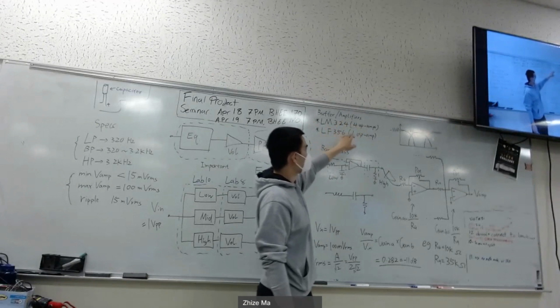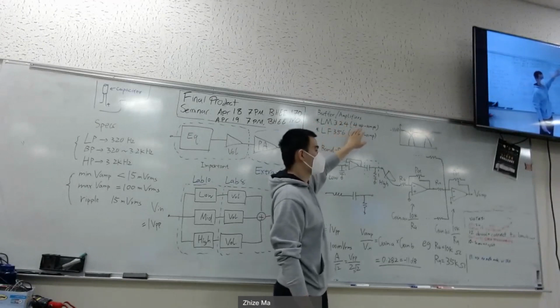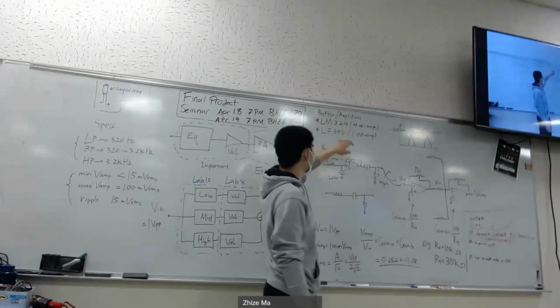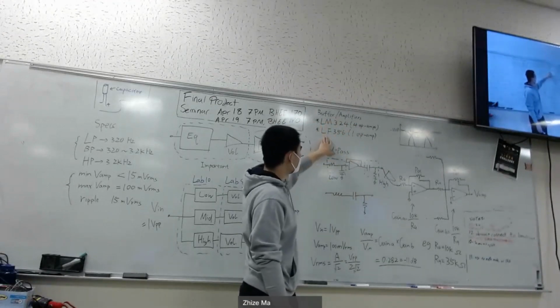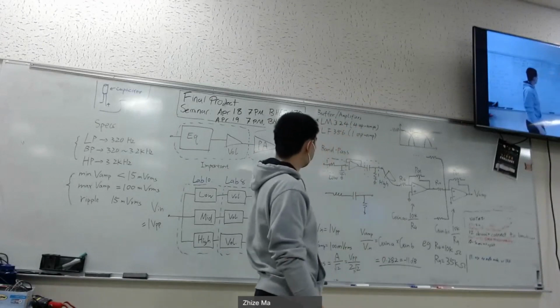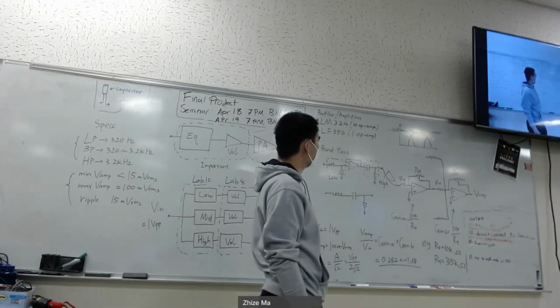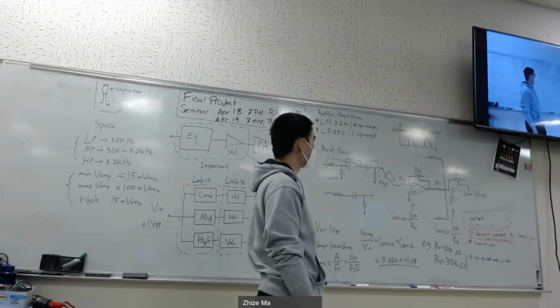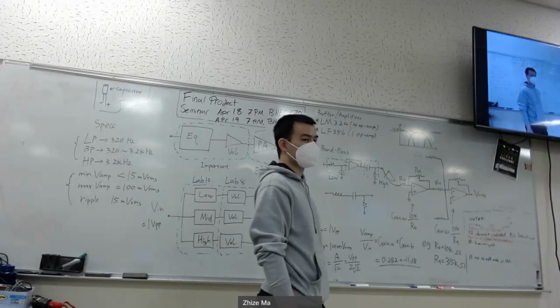I saw students only use 1 op amp and say they don't have enough chips. So there are 4 op amps in the LM324. And also the LF356, there's only one op amp. I think each chip they have 2 of them, I guess. Then in total they should have 10 op amps or 10 buffers. So that should be enough for their project.